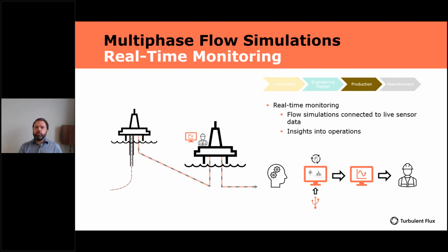For example, if you've been operating below turndown rates and you're ramping it up, you can have advisors that will tell you what surges to expect. The challenge here is that you can't foresee every eventuality, so predefined advisors are not always feasible to use. And you may then be able to have full scenario mode doing that, but you're then looking at one simulation at a time, and that makes it challenging to do true production optimization.